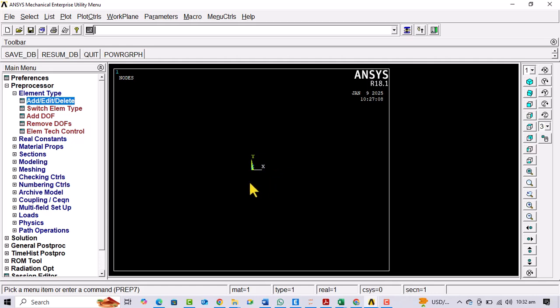We can also use beam elements, but in that case we would have much more complexity in the total stiffness matrix. In the case of LINK180 all the rotations are zero, so we only have axial forces, and all the y components of the forces are also zero, so we get a simplified calculation when using LINK180 as the element type for the truss analysis.